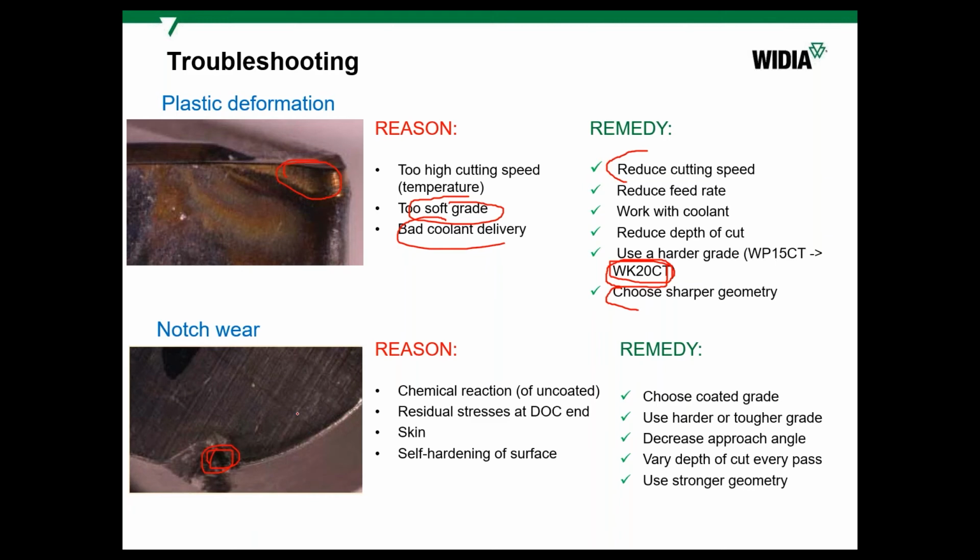Here is a round insert, for example, a ceramic insert. But for example, if we look at our rhombic style, here is a component. Here's the depth of cut. This is the feed. This wear appears somewhere here, at the end of the cutting contact. It's much bigger than the wear here. Here maybe there will be no wear, or just, I don't know, 0.05. You can see the line, but it's not wear.